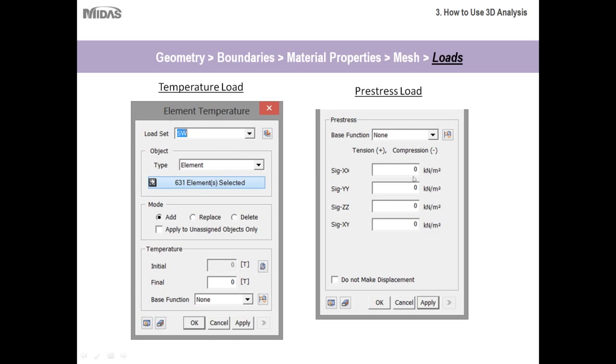And the same with a pre-stressed load. So, for example, if you have something like a beam or a bridge with some pre-stressed tendons, you could simulate that pre-stressed load on those tendons just using an option such as this. So as I mentioned earlier, we'll go into more detail about these special options later on, but I just wanted to let you guys know the options that are available to you. So this is another unique strength of numerical modeling, that you can take more variables into account, and for variables such as this, a numerical modeling approach would really yield good results for you.